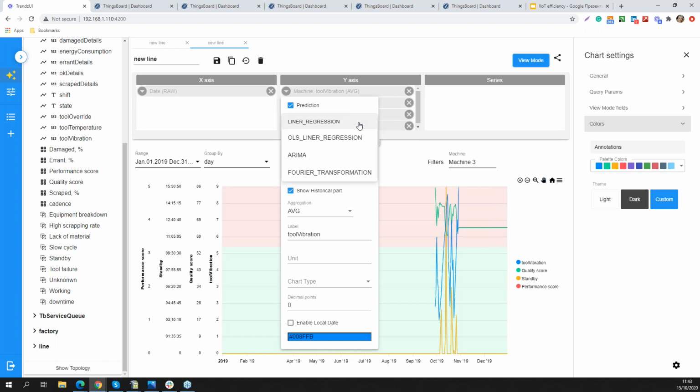Okay, how can we detect a scrapped product and count scrapped details? They are reported by a quality control sensor. In our example, it is an optical sensor that analyzes the image histogram against a reference and then reports true or false. So we are using the camera to detect the scrapped details and count them. Okay, the next question.